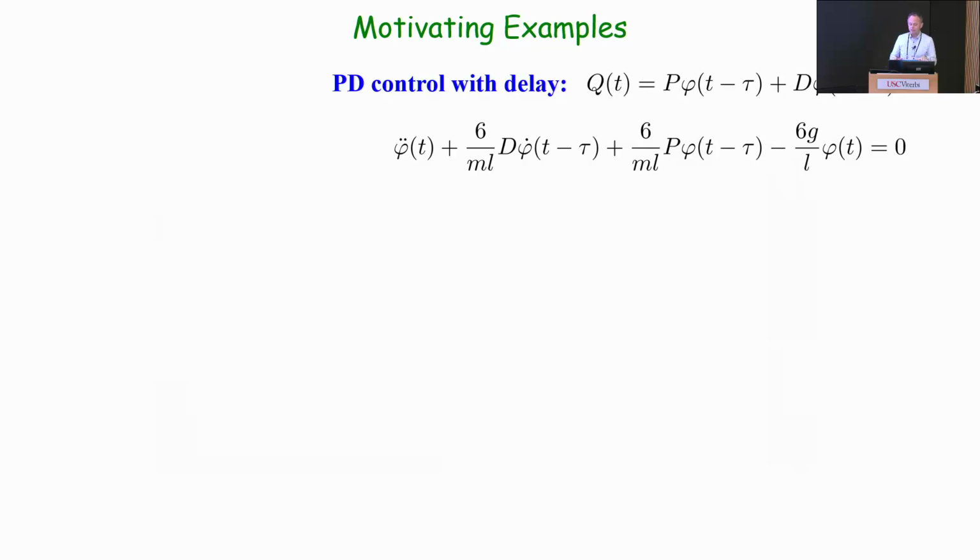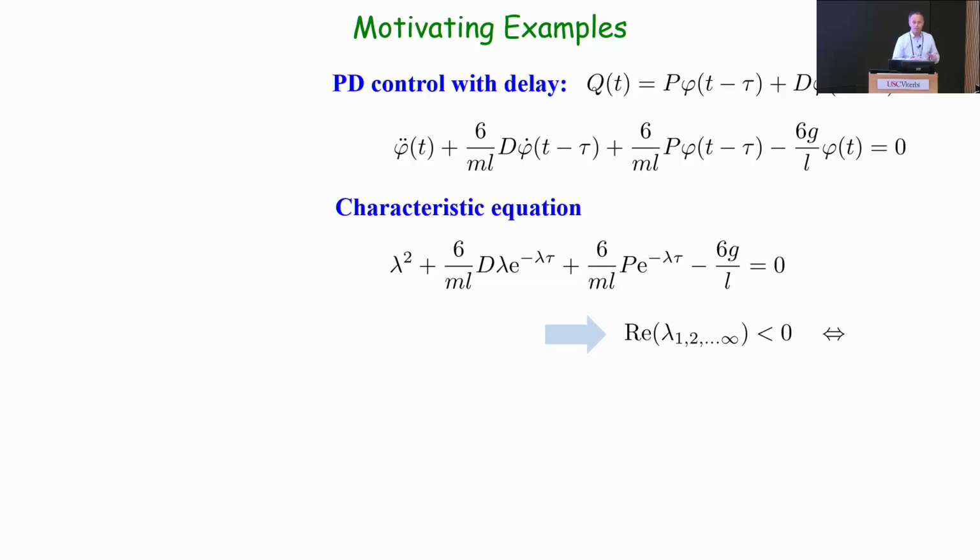And what happens is that your characteristic equation, or your equation, becomes a little more complex with these time delay terms. Right? So you can see now that the control force is actually going to depend on the delayed value of the state and the derivative of the angle. Okay? And if you go through your characteristic equation, then suddenly something really weird happens, right? So previously, I had this second-order equation. I can actually solve it with high school logic.